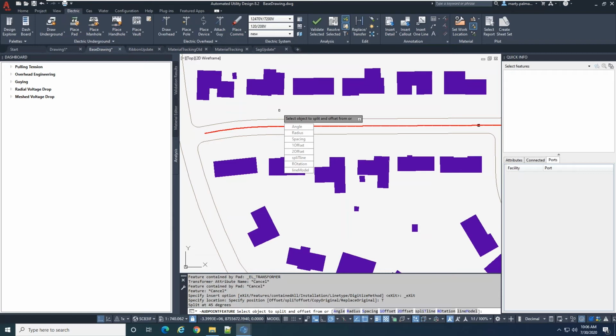So if I have a 4-inch duct, a 4-inch conduit that is going to sweep on a 4-foot radius bend, I may want a 4-foot radius added, some additional buffer in there so that there's room to fit the sweep in.